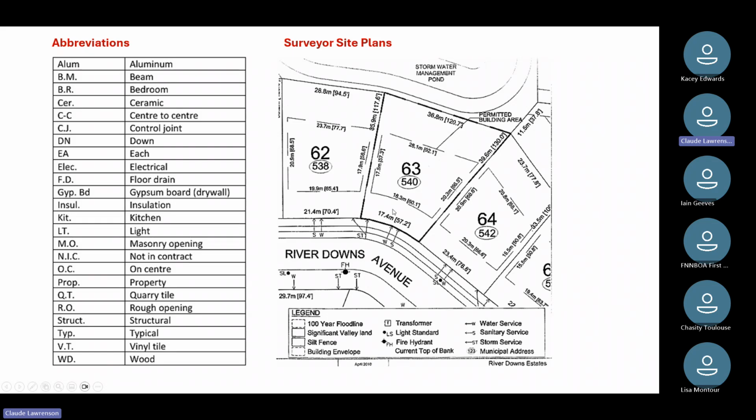What we see here within the property is a set of boundaries. And when we talk about municipalities, we get into what they call setbacks. So for example, there needs to be a certain amount of space left between the property and the edge before a house can be built from here over to this particular setback here. In other words, there needs to be spatial separation between building units to reduce the spread of fire. This is part of zoning and the zoning application, and in this case these are residential building lots.